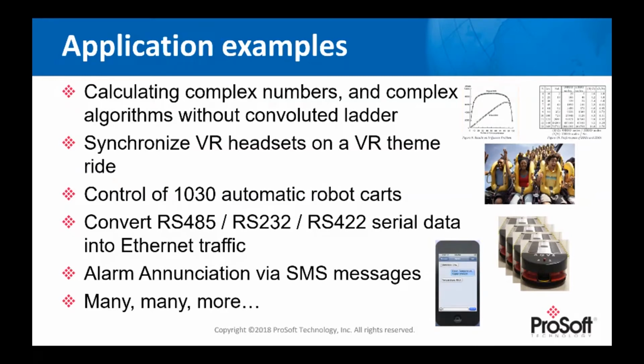There was a case where we had AGVs running around the plant floor, I think 1,038 of these devices. They were trying to control them with just a ControlLogix processor and an Ethernet card, and quickly discovered that's not happening. With the LDM module, they were able to have all of those devices communicating over UDP, receiving their coordinates and also receiving packets back telling them where to go.